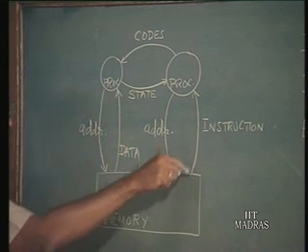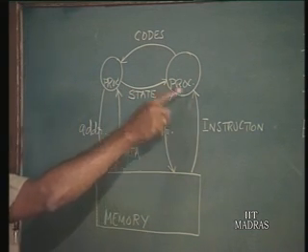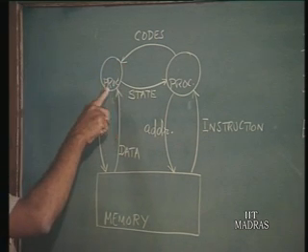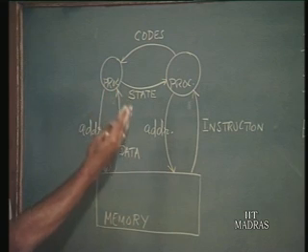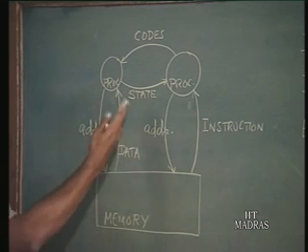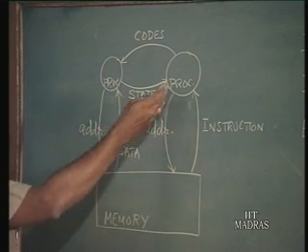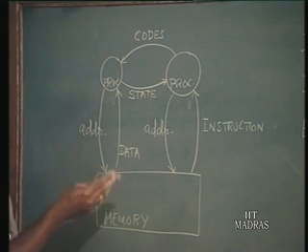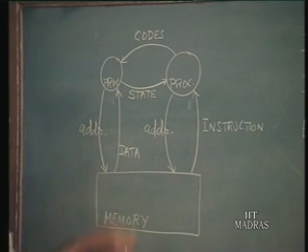Let us say the instruction is an add instruction, and after it had got the two data A and B, the addition may result, let us say, in a carry or an overflow or something. So, that state it has got to register, because based on that the next instruction will have to be fetched and so on. So, that is the state we are talking about here.